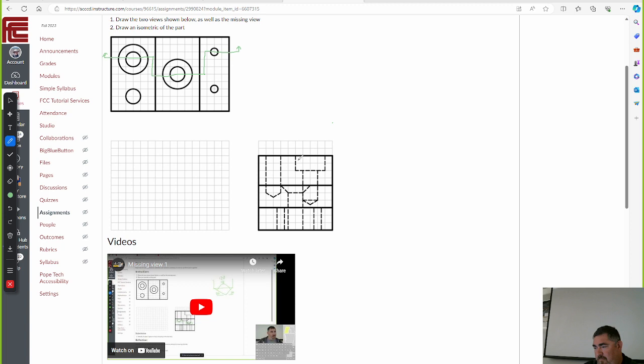We could see now these hidden lines, when I copied over. What's going to happen to them now once I do a section? They're going to become what? Solid. So we just changed the layer from hidden layer to object layer. And then we do that to all of those. Is that it? Is that all we need to do?